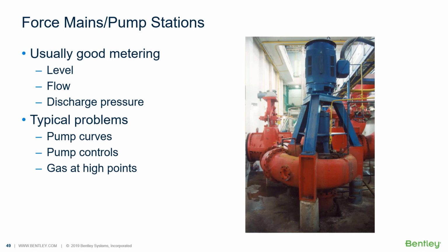Some of the problems that you deal with are the pump curve is no longer right, or it never was right. It's the wrong pump curve. You need to find that original pump curve. And that sometimes takes a good bit of work, because they got the pump curves and the pump was installed, and you come in there and ask where that pump curve is, and they say, oh, Charlie used to keep those in a drawer on the right-hand side of his desk, but he retired in 2012, and I don't know what they did with his old files. Where are his old files? And so you have some of those issues, and then you also have to learn about how the pumps are controlled.